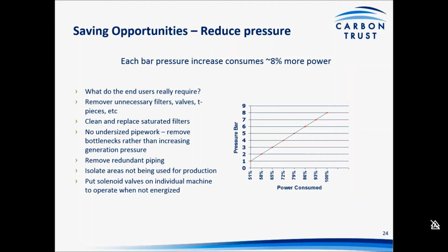To improve the pressure, there's a handful of things you can do. Make sure you keep the sizing of the pipework as large as you can. Remove any bottlenecks or obvious restrictions, any joins from the larger ring main to some of the processes, and if you've any old redundant piping, make sure that that's sealed off from the main system.